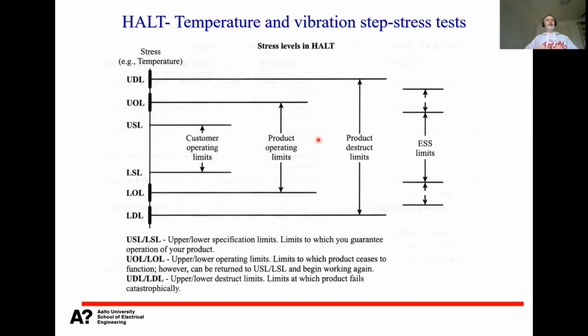So if you would be testing, let's say again the ceramic capacitor, then most probably your HALT testing could be that you use simultaneously high voltage and then temperature. And you start increasing the voltage together with the temperature and see when the breakdown comes. So when the capacitor is, let's say, burning. So it could be as well that it could be high current, as you said.